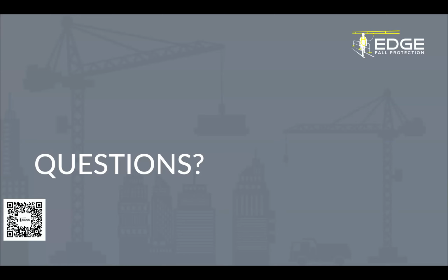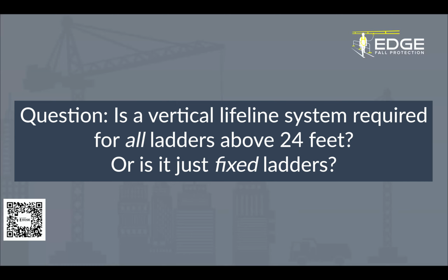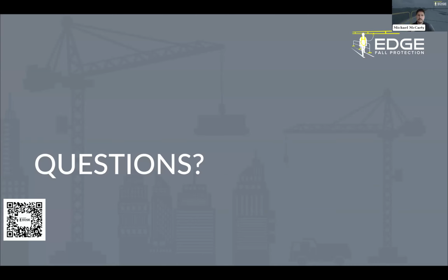The first question we have here is from Ernest. He is asking, is a vertical lifeline system required for all ladders greater than 24 feet, or is it just fixed ladders? Oh, that's a great question. Fixed ladders over 24 feet need a fall protection system.